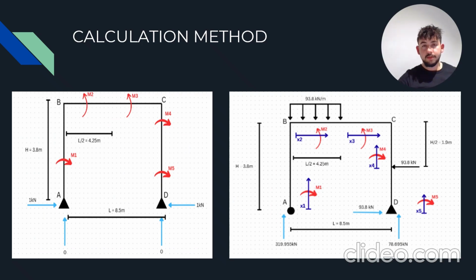Moving on from the initial calculations for the reaction forces, the next step required me to visualize the structure in the way I have in the right photograph in the slides. I had to take 5 different cuts at this frame and analyze the internal moment forces at each one. By doing this, I was able to calibrate the moment equations for each cut, and similarly, I had to also do this in a way which I have idealized the structure in a unit force manner.